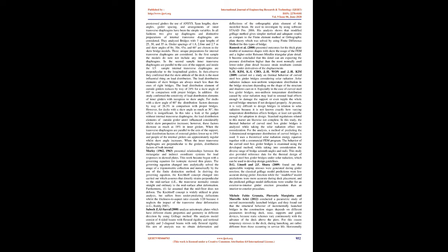In deriving the governing equation, the Kirchhoff theory was applied, which assumes that straight lines perpendicular to the midsurface, i.e., the transverse normals, remain straight and normal to the midsurface after deformation. Furthermore, it is assumed that the midsurface does not deform. The Kirchhoff theory is widely used in plate analysis, but suffers from under-predicting deflections when the thickness-to-side ratio exceeds 1/20 because it neglects the effect of the transverse shear deformation, e.g., Reddy 2007.